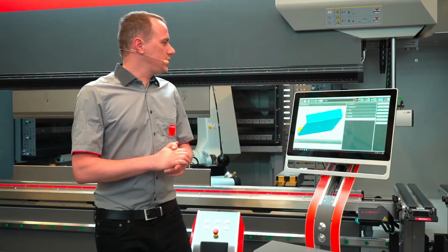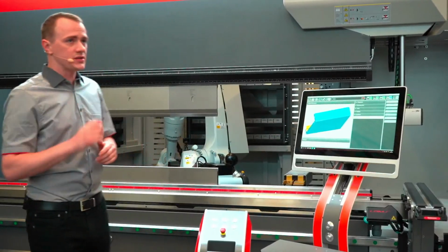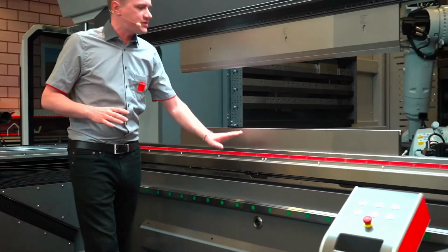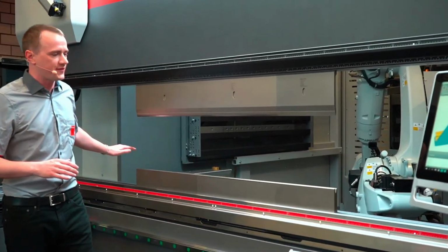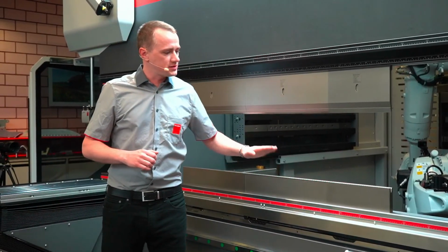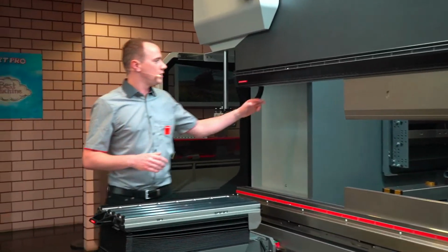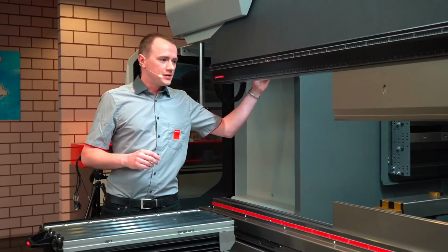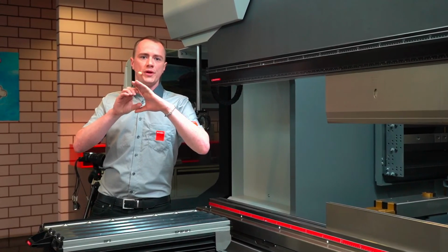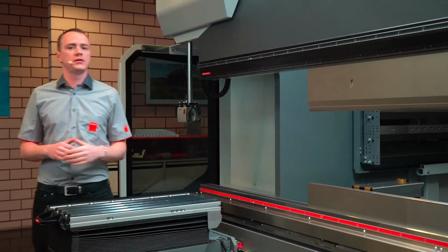Now, this machine is equipped with a bunch of standard features, which I'd like to show you first. As you may have seen in the video already, we have our crowning system. The crowning system keeps the level of the tools on the table always flat, always straight. So even if you bend very strong and tough material, the table doesn't tend to bend downwards and always stays straight. What we also have is side frame compensation. When we put some pressure on this C shape, the side frame will open up and the machine can compensate for this by already knowing how much further it has to travel from the calculated position.